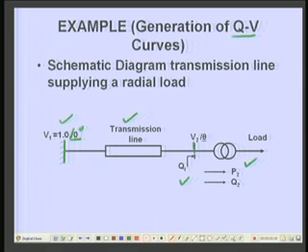At the load bus, where the load is connected through a transformer, we are injecting a reactive power Qi. Qi is the reactive power injected at this bus. Our exercise is to plot the QV curves for fixed values of real and reactive power supplied.